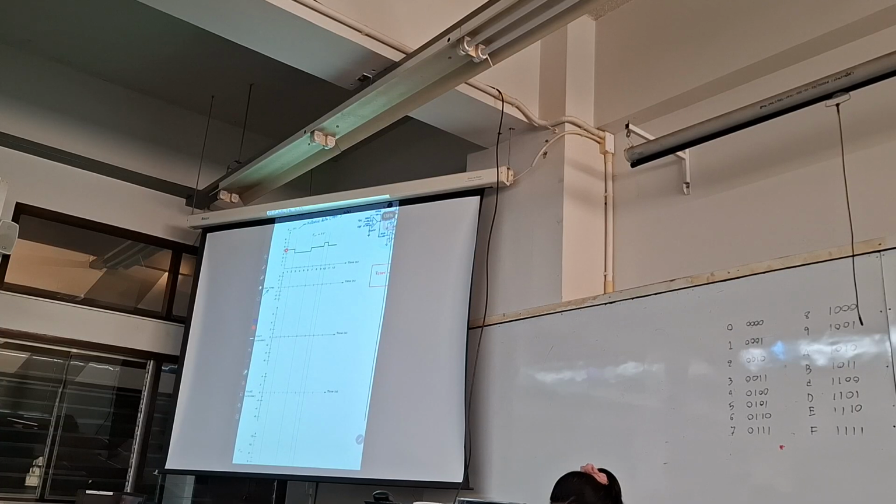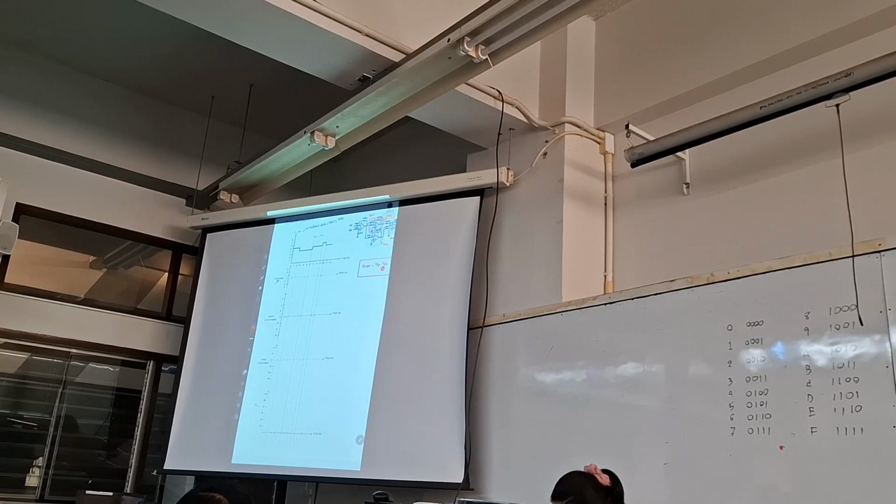So what is this? 5. We have a set point at 5 volt. It is the PV value. So what should be the answer here? V error is equal to set point minus VPV. Set point is equal to 5, VPV is equal to 5. 5 minus 5 is equal to 0. So do we get something like 0 here? 0.